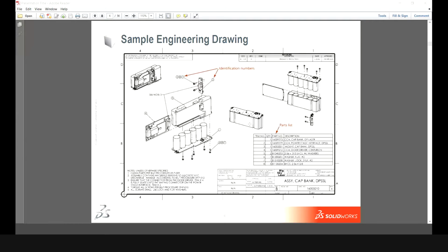So this part here is the BOM, bill of material. Okay, there is a block, a table, and then columns with the important info: item number, quantity, part number, part list, and description. Okay, left side board. Here are your notes. Okay, let's say the customer requests some information, and then your title block. Okay, this is a drawing. Same as in industry. Tomorrow if you get a chance for LI at a manufacturing company, R&D, okay, same like this.